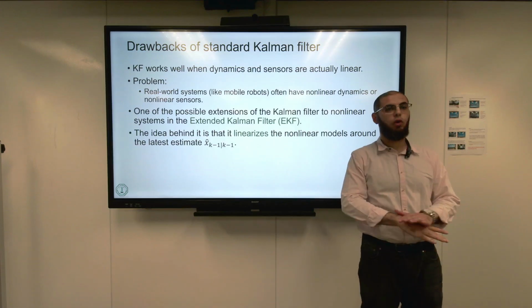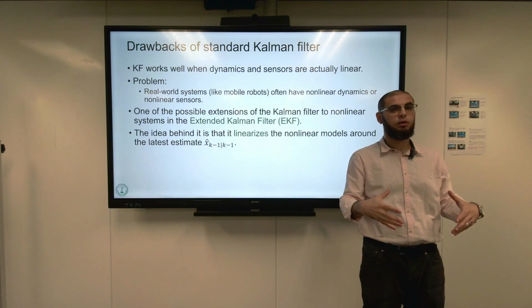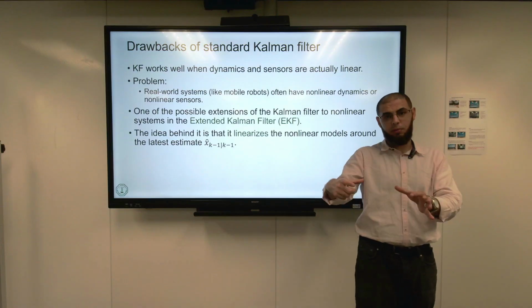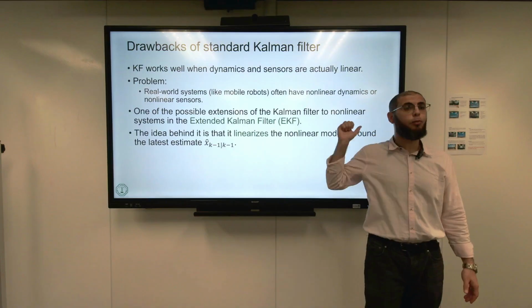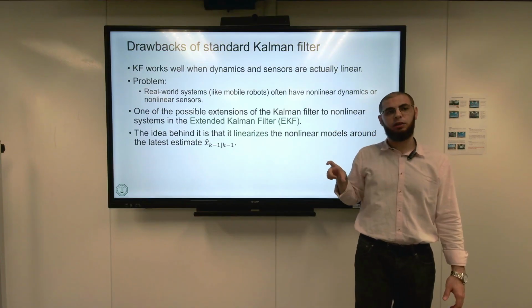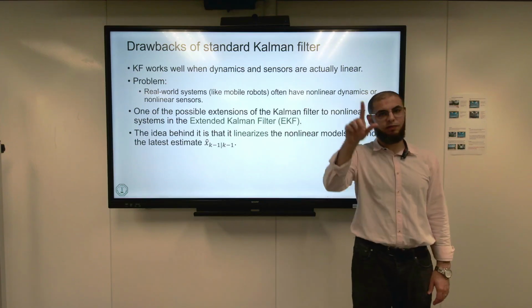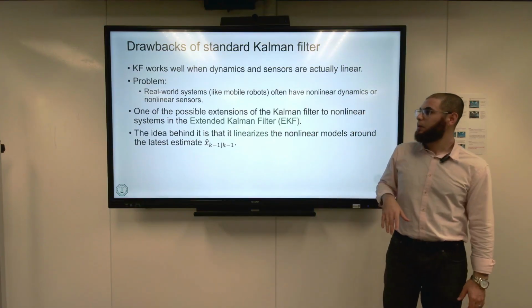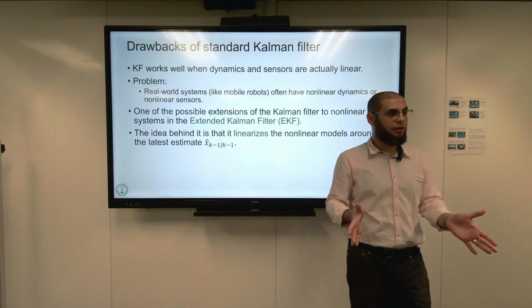In real life, all of the camera, how the camera affects the dynamics of the robot, and even the accelerometer itself, the accelerometer and the gyroscope and the magnetometer. If you go back to the lecture when we had the sensor modeling, on topic number 3, you'll find that there were sines and cosines all over the place because of the rotation matrix, which means that everything is nonlinear there. So there are many ways you can treat nonlinearities with the Kalman filter.